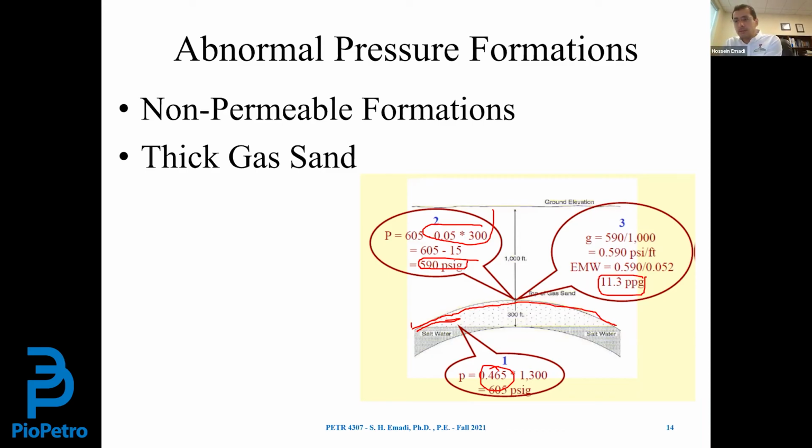If you are 100 psi or 200 psi underbalanced, less formation fluid can enter the wellbore because delta P has a direct relationship with Q, the flow rate. The more underbalanced you are, the more formation fluid, at a higher rate, can enter the wellbore, so you have less time. The second factor is how deep you are. If you are drilling at 1,000 feet or 10,000 feet, the deeper you are drilling, the more time you have.